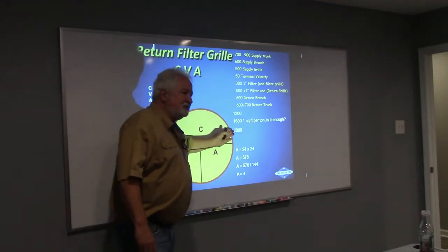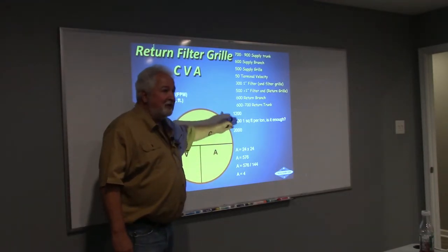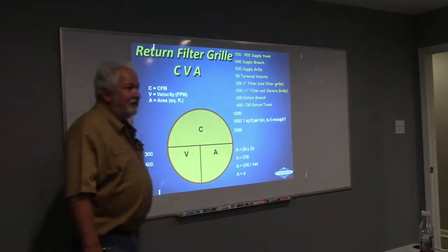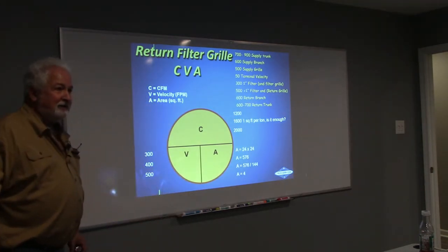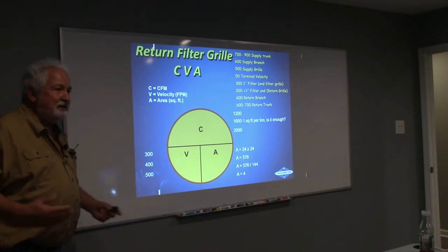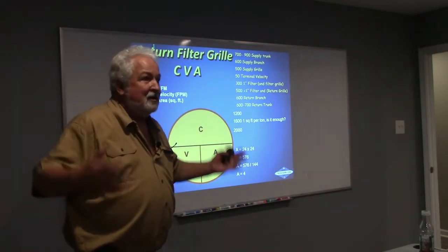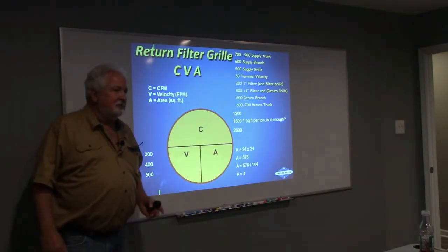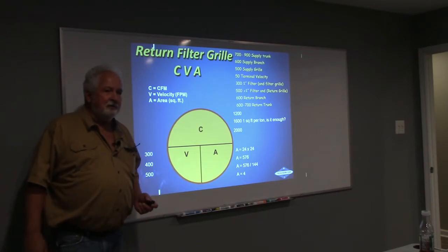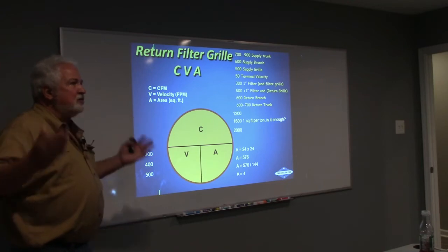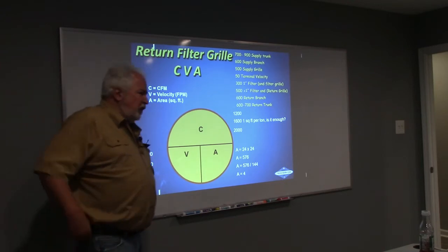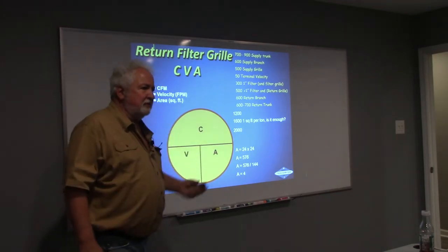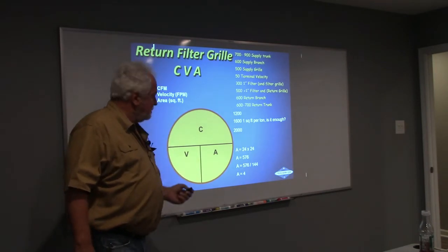What about this 2000 CFM? If I put this 24 on a 5-ton unit, how fast would that air be moving? Real fast, somewhere about 500 feet per minute, is that right? Wow. So you're getting it. What's going to happen to the dust going to that filter? Straight through. It's going to go to the blower and stick to the wet coil. Cool. When somebody says, oh yeah, you can do it because I've done it for 40 years, I don't want you to buy into that. I need you to be smarter than that. Do you like this? Cool. All right, let's try it again.